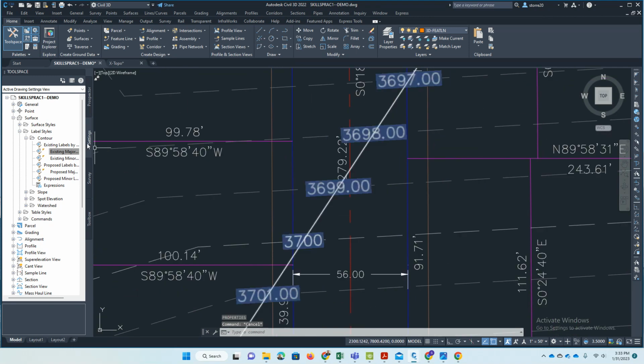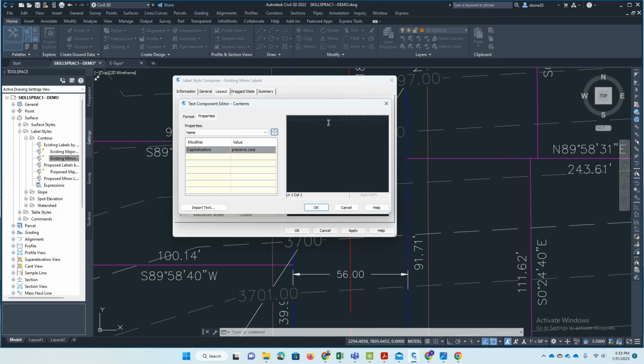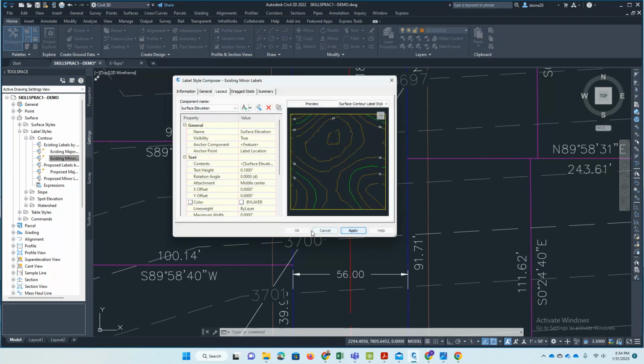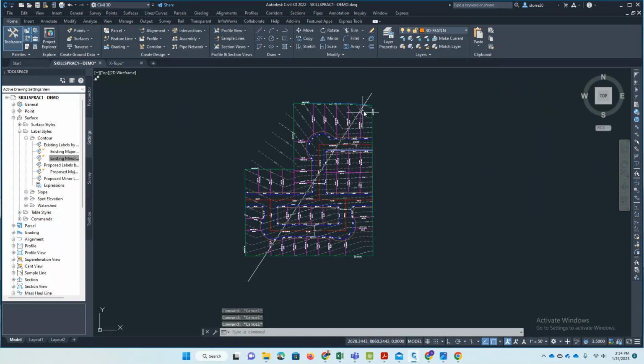Of course, that was the major. I guess we have to go to the minor, do the same thing, edit that surface style. Go in here. Don't forget to select the little code, delete the code, change that to the nearest one, and reinsert the code. Okay. So that's pretty much what I would do for that surface style.